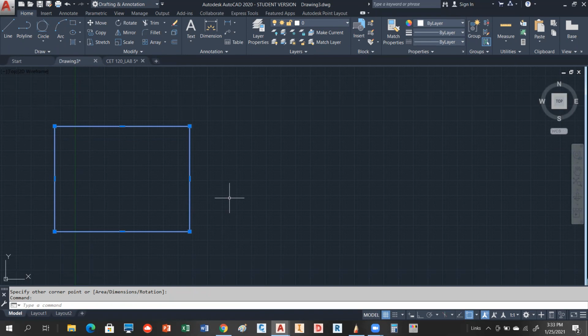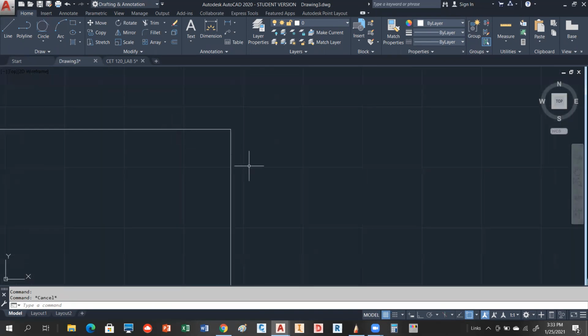One of these things is to give this guy width. Now, the way width works on a polyline is it's going to use this as the skeleton, and it pulls the object out this way, and it'll pull the object out that way. So think about that as a framework or a skeleton, and it just pulls it out.